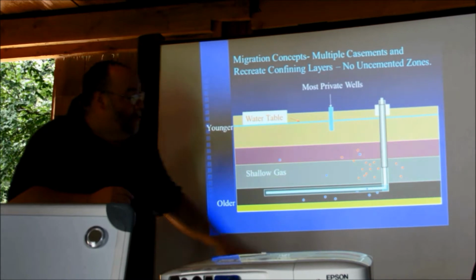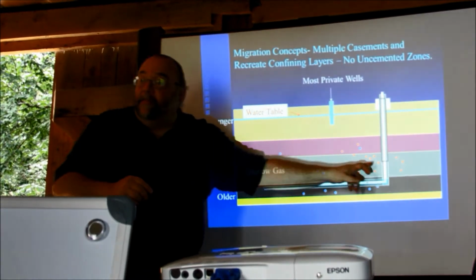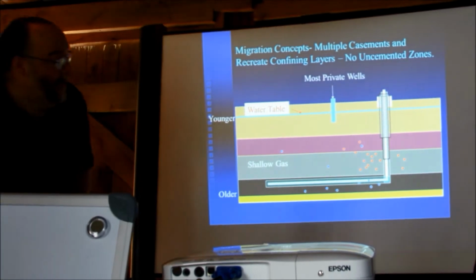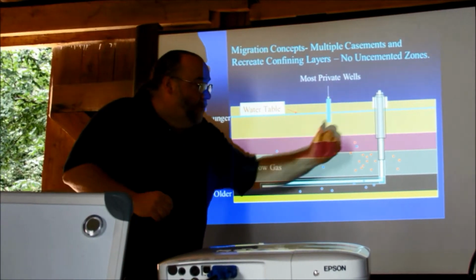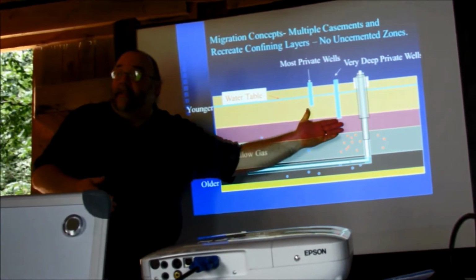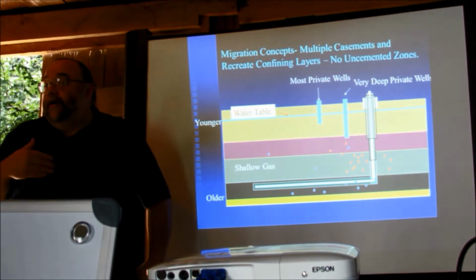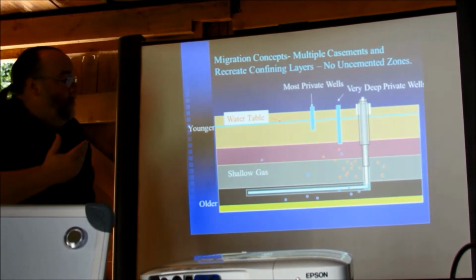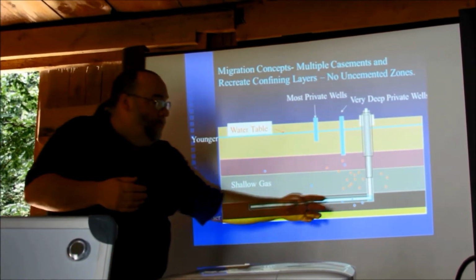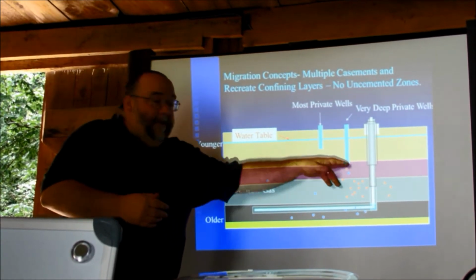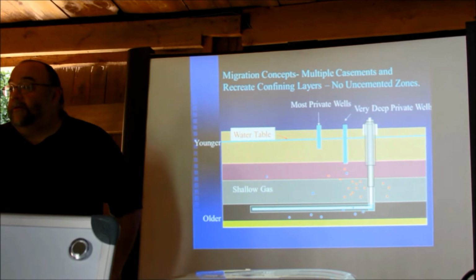So one of the things is sealing off, when you get in those zones, putting extra cement and casing, sealing that off, having that extra barrier up near the surface rather than run deep private wells. So these deep private wells that are in saline water now become the next pathway. These become great locations that, if you're concerned about the hydrofracking having an effect on the pressure, are places that you want to monitor.